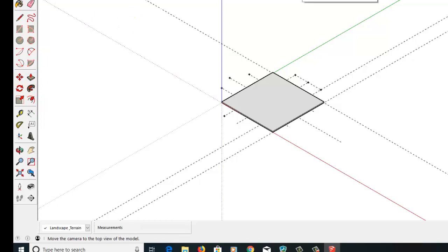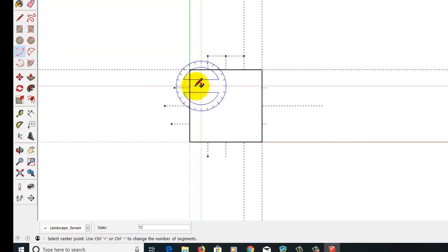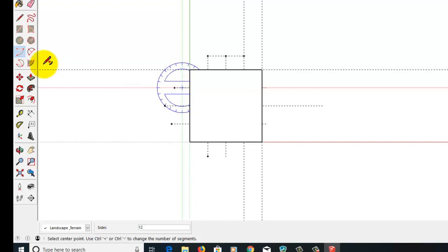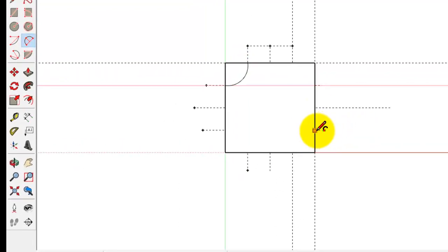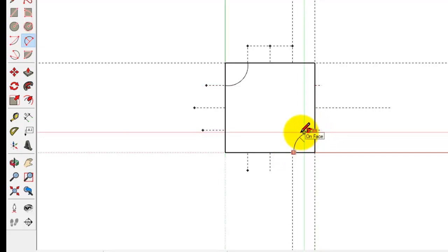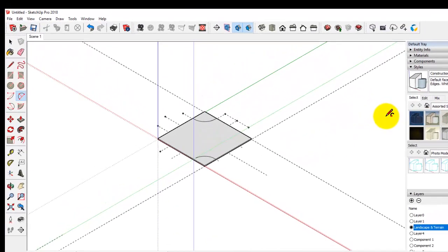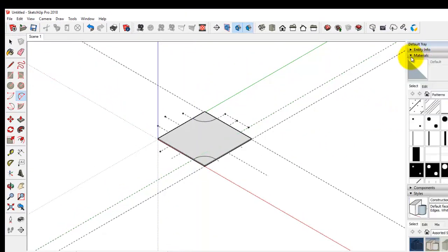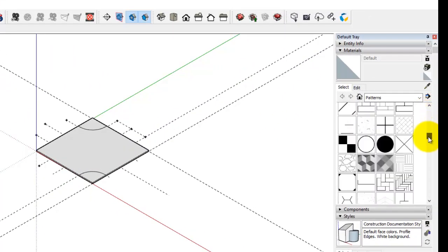To come out of the tool, sometimes it's best to hit escape, but go to the tool, and let's choose that we select the edge. We can choose whether it's going to be an inverted curve or an external curve. In both cases, I'm going to select the internal curve. So view it in 3D. Again, I can go back and do a bit more dragging to lift up the elements of the slab.